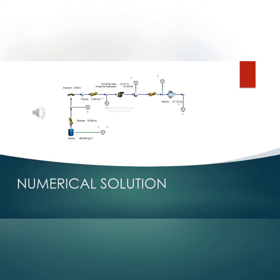The flow rate was constant at 220 meters cubed per hour throughout the system. Minor losses at the elbow were added to the system. The velocity at the nozzle was found to be 31.12 meters per second. The pump generated an overall power of 43.349 kilowatts from a pump head of 24.161 meters.